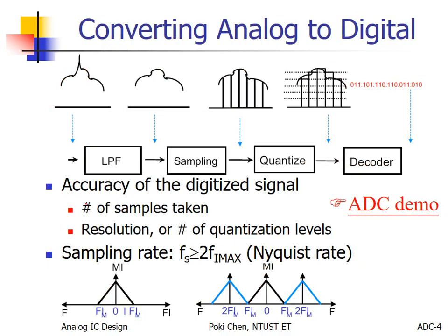And this is for even better understanding. Yeah, a more detailed flow. From the beginning, you have low frequency component, high frequency, very high frequency component in your input. But before we do such kind of analog to digital conversion, we always apply such kind of low pass filtering. Yeah, why? We would like to filter out all those frequencies our ADC cannot handle.